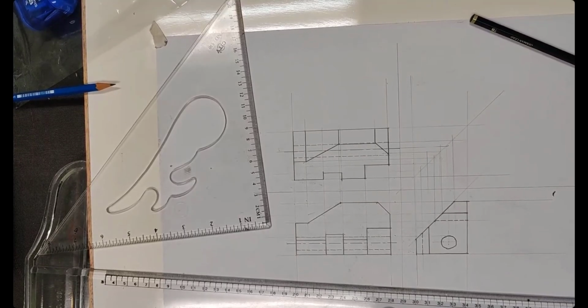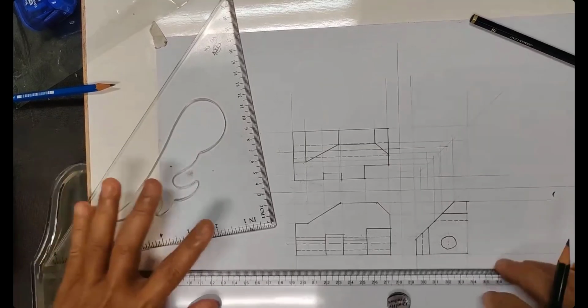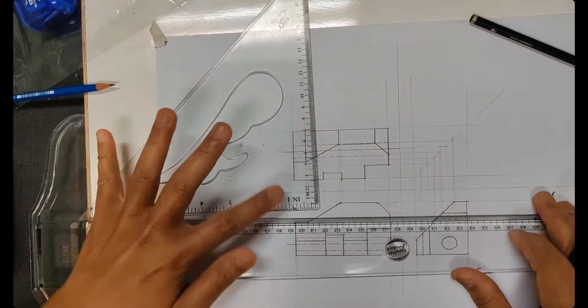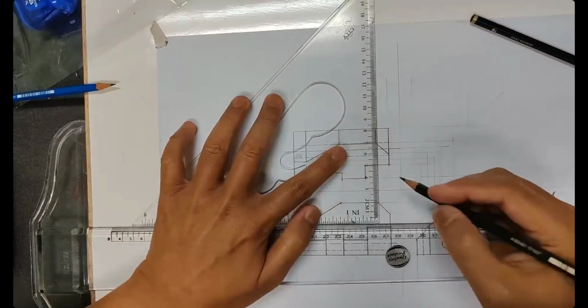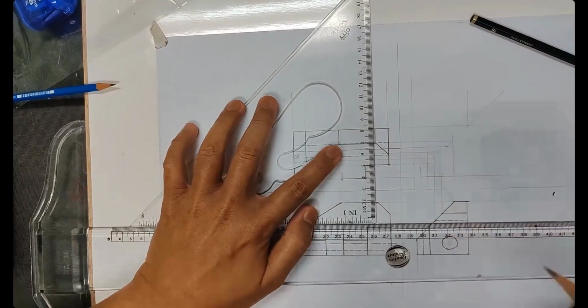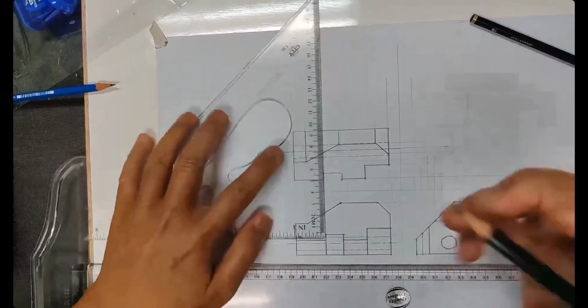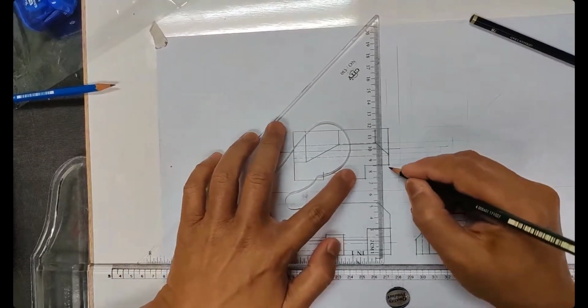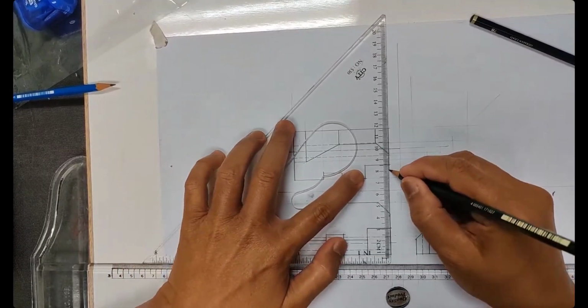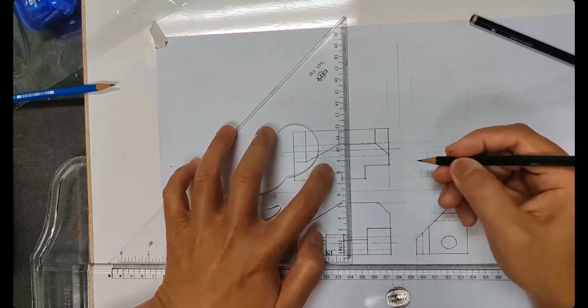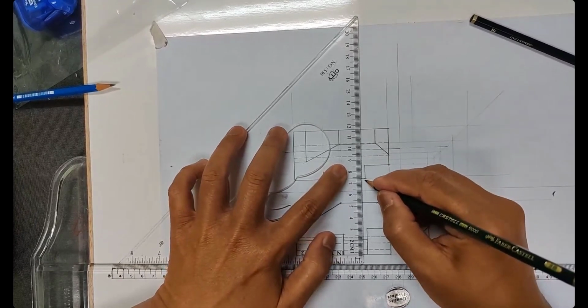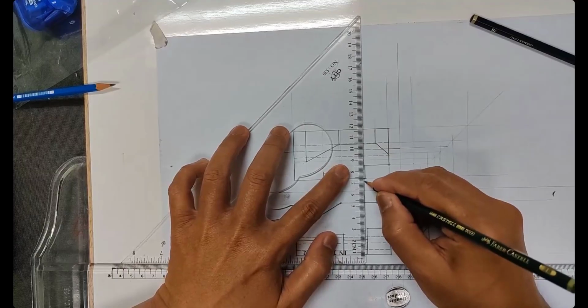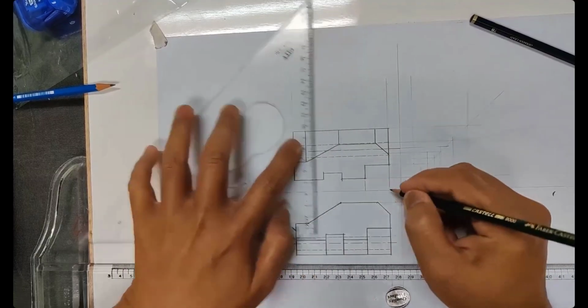The cutout of 10 can clearly be shown by the top view. So make the top view. Look at me, okay, top view. So, what is dimension? 2B, because the middle one, okay, 2B. Do not touch the object. 1 millimeter gap, I make an extension line. Can you see this one, extension line? Do not touch this corner. So I'm not too close, about 2 letter height.